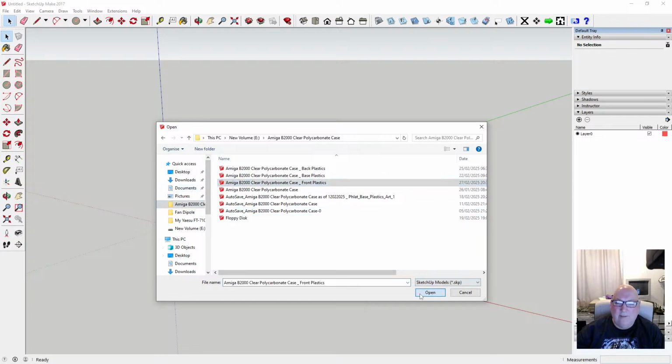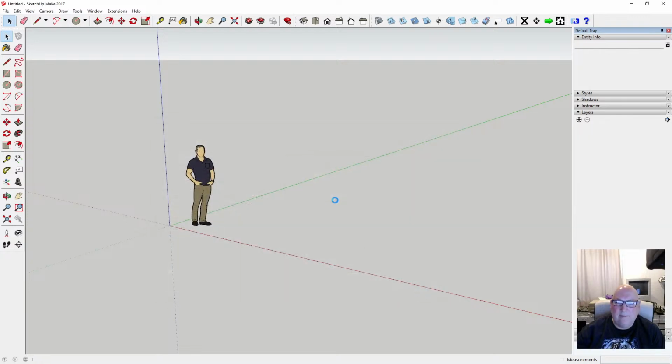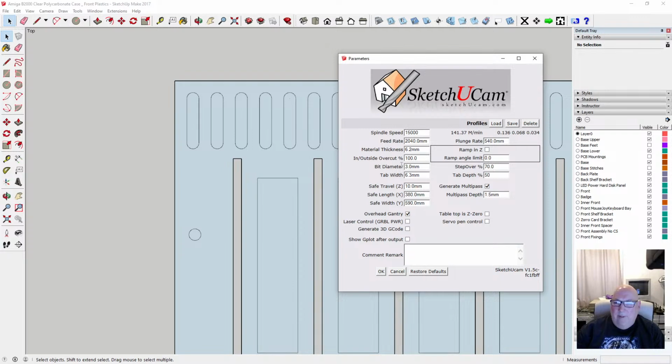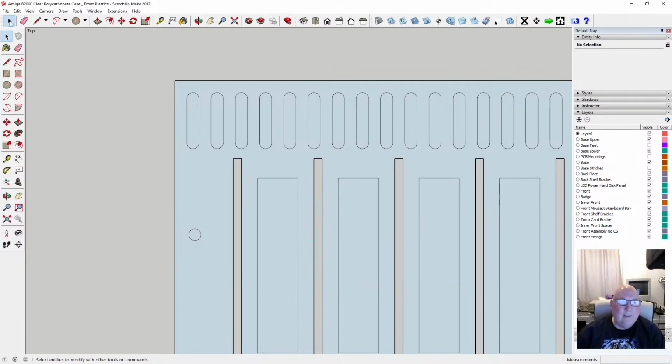Right, the milling bit is smaller. Okay, so I'll go here. The milling bit is 2.768, 2.8. Okay, save it. And go over to inside cut. Okay.